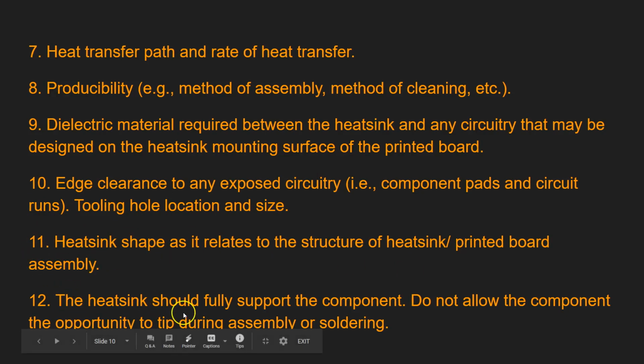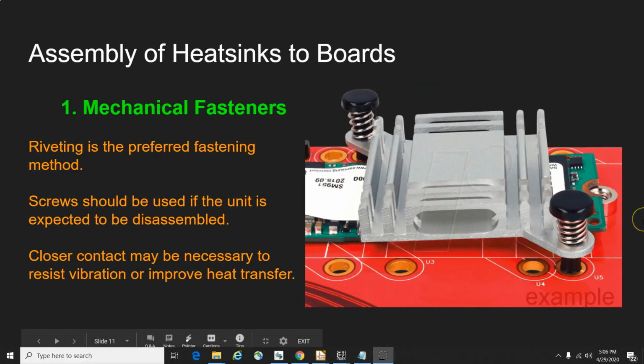The heat sink should fully support the component. Do not allow the component the opportunity to tip during the assembly or soldering. So I think all these considerations were pretty straightforward, and I hope you understand what it says. Now moving on to the next slide, assembly of heat sinks to board.